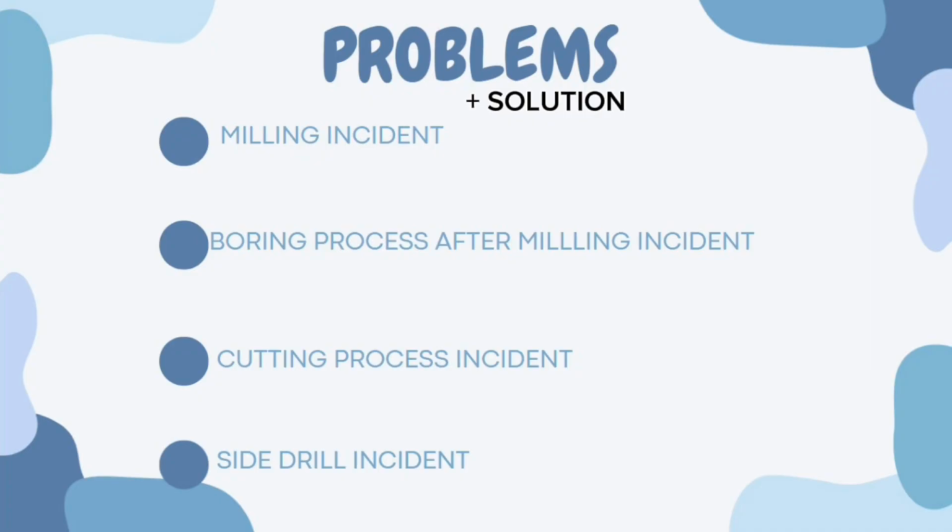Another problem that we faced was drilling a hole on the side of our workpiece. While drilling on the side of the workpiece, the drill almost didn't go through and almost snapped. Because the angle is quite difficult to drill through the material, the workpiece had a massive snap feedback to the working station, and because of that, there's a defect on the hole that was made on the side of the workpiece by the drill.